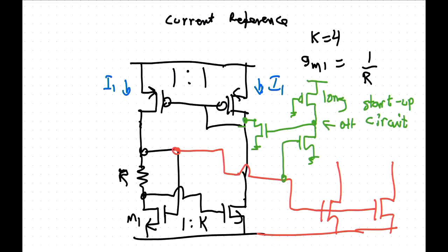The main idea with this is that it doesn't matter how much current flows in this part of the amplifier, all of that signal current makes it to the output, because it doesn't go through the current mirror. That means you can put most of your current in the diff pair. Then you've got to scale down this current, so you get a small current over here, if you have the same total amount of current in the amplifier.